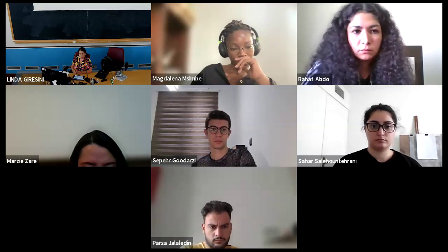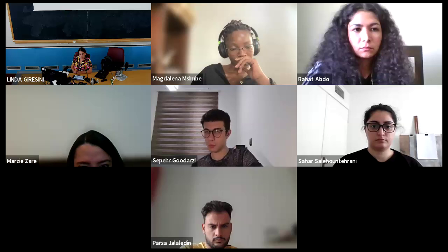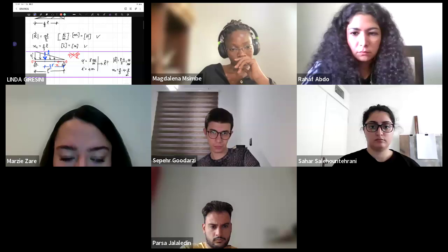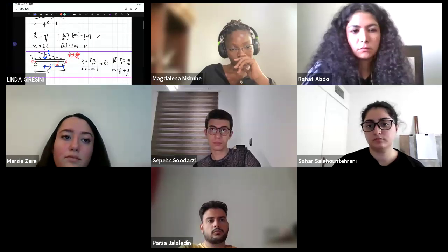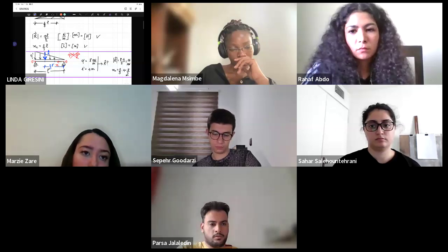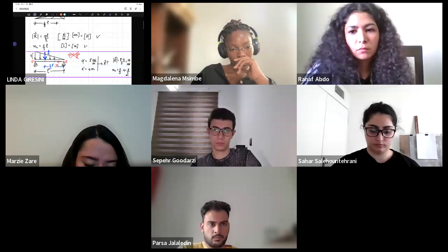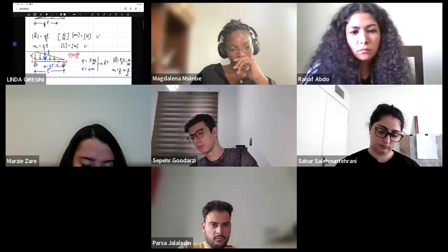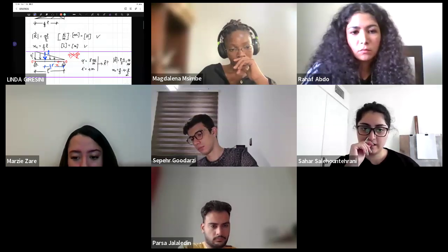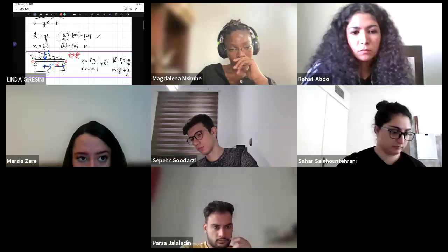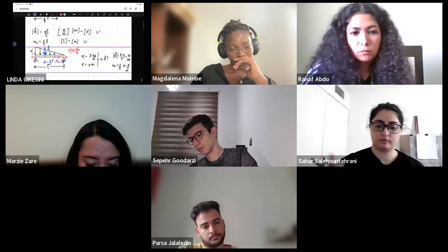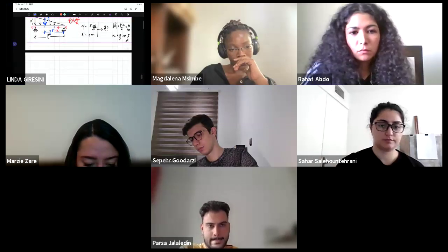Okay, do you have any questions? Yes? 2/3 is valid whenever you have the triangular shape and the origin at q equal to 0. Otherwise, you can also solve it by putting your axis origin on your left support, but the expression will be different.